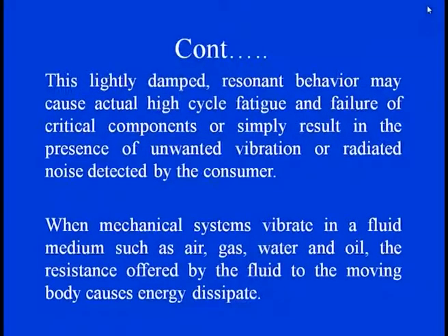Because this lightly damped or resonant behavior may cause high cycle fatigue and failure of these components, or it results in the presence of unwanted vibrations, or it provides the domain for the radiation of noise which can be detected easily by the receiver. As we have seen, large plates are always going under high cycle fatigue or failure because of these internal features.